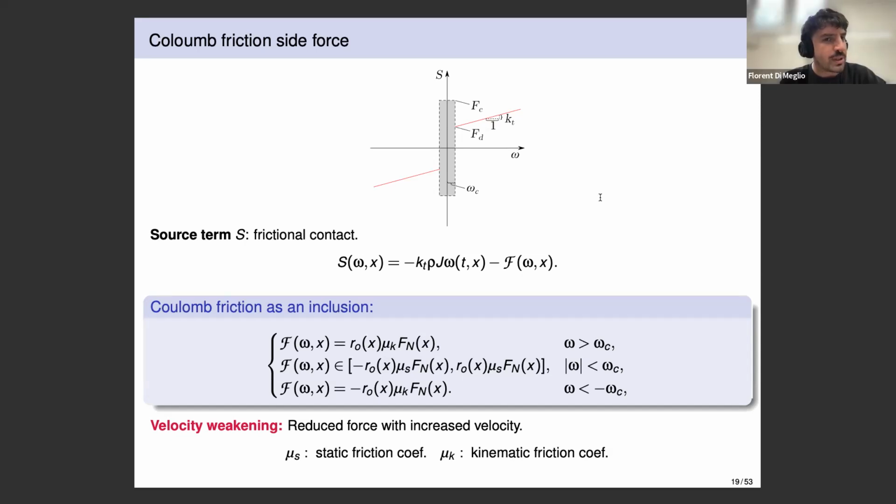Okay, so actually Roman is by far the most qualified to answer this question. One thing I will say with this model is that it has a very limited number of parameters needed to describe it. And with the uncertainty that you have on the exact shape of the Stribeck curve, one of the biggest benefits of using such a simple model is that you basically have 3 parameters to calibrate. So that's one advantage. And the omega C here really helps you have good numerical performance, in the sense that you avoid a lot of jittering effects and so on. Yeah, numerical instability. Yeah, exactly.